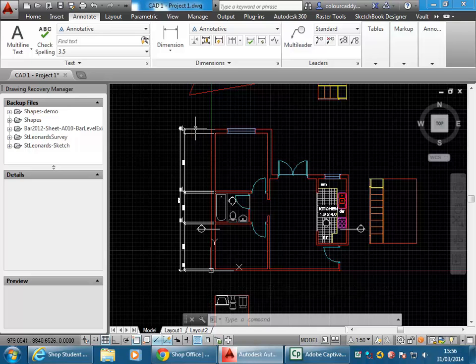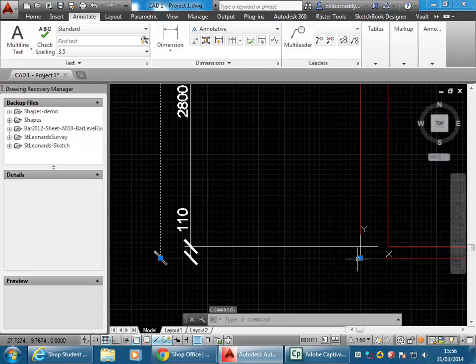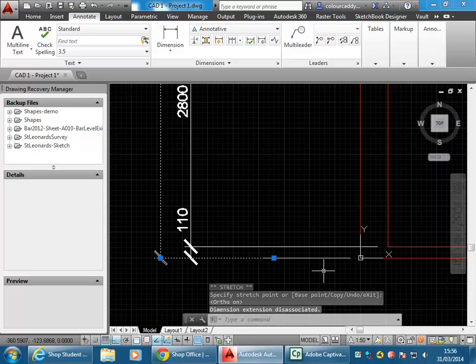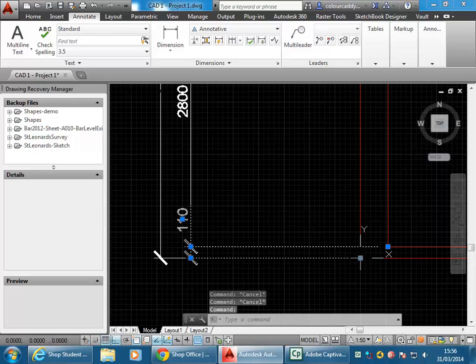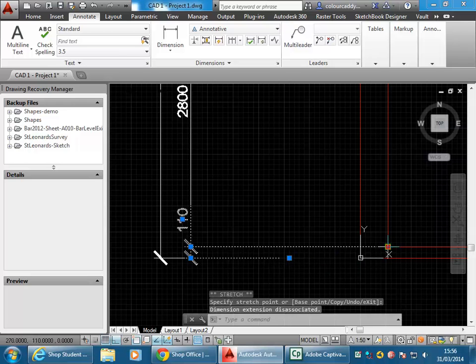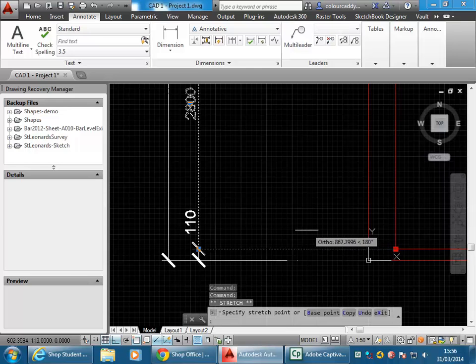But you can see that now my dimensions are going over the plan, so I'm just going to do one last thing. I'm going to select all of those, or just select each one as I go, and you can always use the grips for now just to bring them back to the left. It's going up and down, so I'll turn ortho on as well, just to keep that in a straight line when I move over to the left, and then I can just keep using the grips to adjust those manually, and just by eye even is fine if you drag them each over.